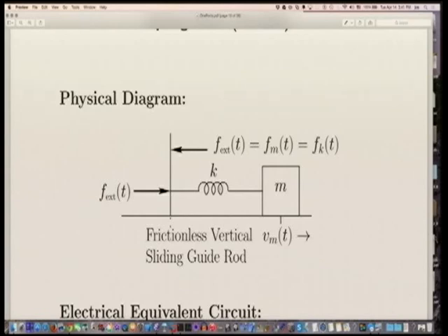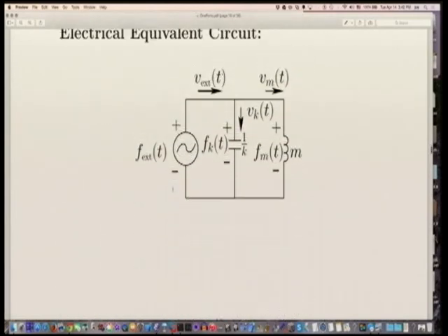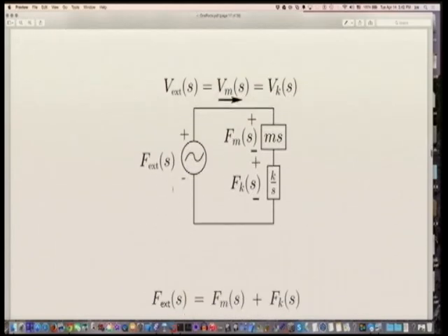All right. So that's assuming it's a linear time invariant system. And in those cases, we can describe a port by the port impedance. And so the port impedance is all we need to represent the system. And that means I could replace this with any simulator of that impedance, and the force would see the same load and behave the same. For any applied force, we get the same velocity at that driving point. So that's a port.